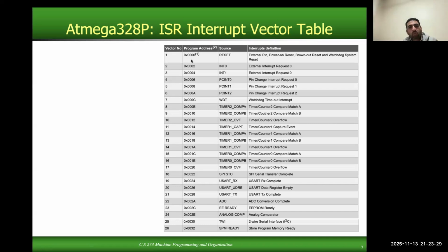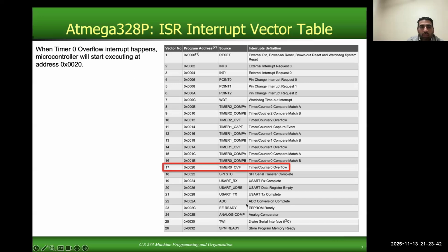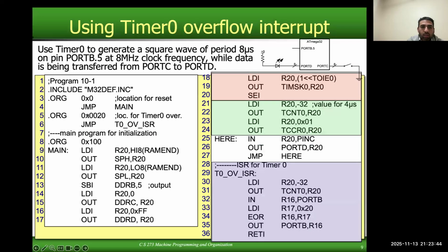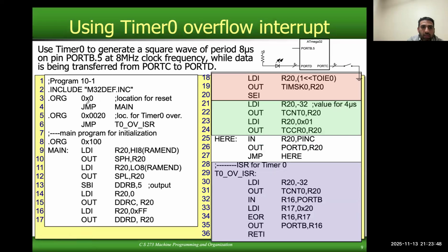Now, that's why we are putting jump main in the address 0, so that when this instruction is executed on reset, the control immediately transfers to our main program here, right? We are saying jump main and then it will start executing from this point. Okay.